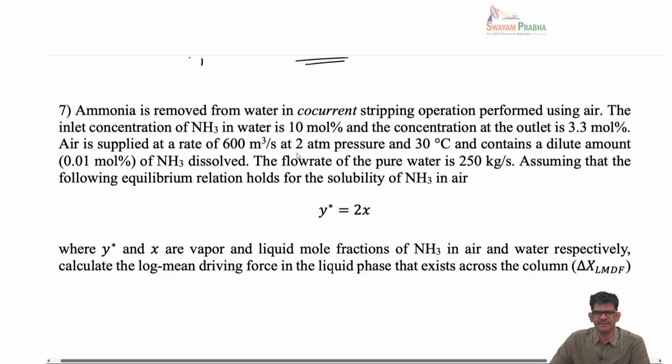It illustrates the driving force calculation that we generally do in heat transfer. In heat transfer, we calculate the log mean temperature difference for co-current and counter current. In the same way, in one of the classes I mentioned the analogy between heat transfer and mass transfer with regard to the average driving force. For example, in co-current, there will be a large mass transfer driving force in the beginning, and then this driving force will diminish towards the other side.